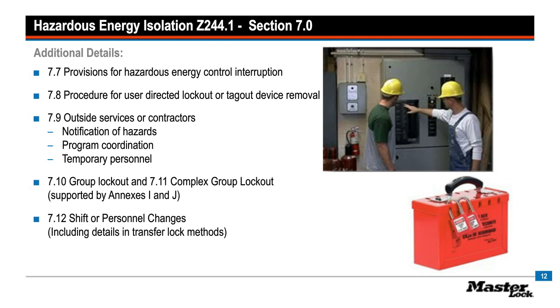And there is also information based on how to remove lockout, tagout devices through a user-directed process, and that is a coordinated effort between shift and contractors and maintenance personnel. Good detail there that can be very helpful, I think, to either reinforce good practices you have in place right now or suggest better methodologies.